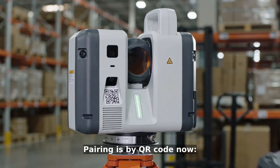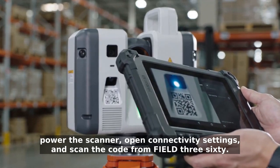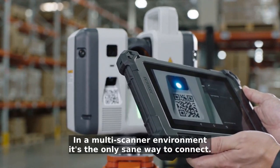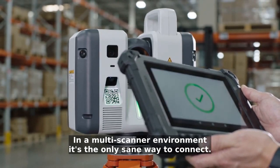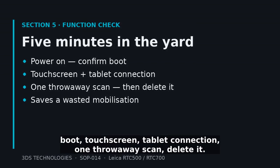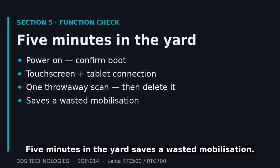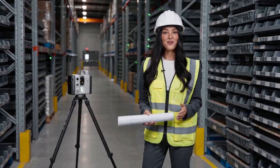Pairing is by QR code now. Power the scanner, open connectivity settings, and scan the code from Field 360. In a multi-scanner environment, it's the only sane way to connect. Finish with a function check. Boot, touchscreen, tablet connection, 1 throwaway scan, delete it. 5 minutes in the yard saves a wasted mobilization.